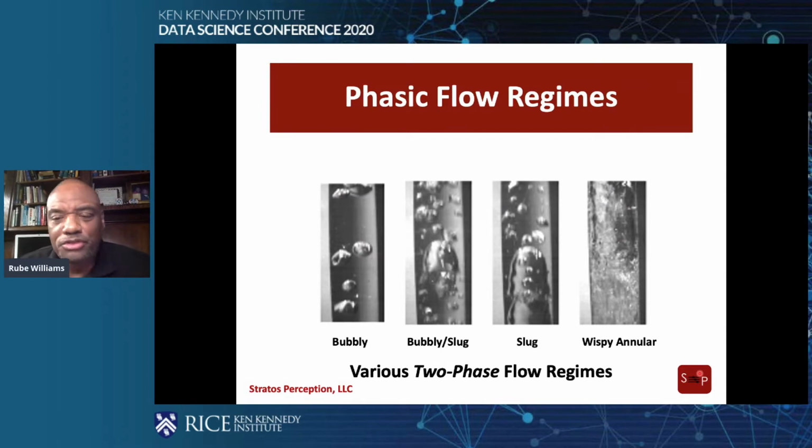The problem with two-phase flow, this is flow with a vapor phase and a liquid phase, is that there are these phasic behaviors, these bubbles, these different sizes of bubbles, distributions of bubbles, we call them voids. And they cause these different flow regimes that we might label according to what we see. They're labeled by inspection: bubbly, slug, things like that.